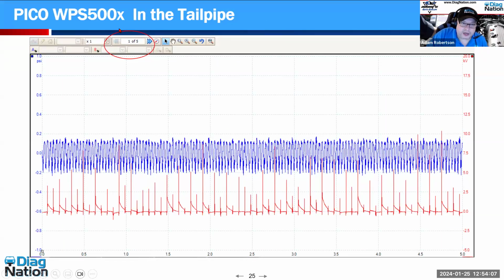I have, as I circled up top, 5 pages of information. Now, guys, this is a waste spark ignition system. So on the bottom, I have synced to one of the coils. So there's true fire, waste, true fire, waste, true, waste, true, waste, true. And in typical lab scope fashion, sometimes it's a little bit hard to make out the voltages that get described. But looking at this view, it's very easy in most cases to see the true fire, the waste, the true fire. And that is going to be cylinder 1's fire. That's the waste, and that's cylinder 1 again.